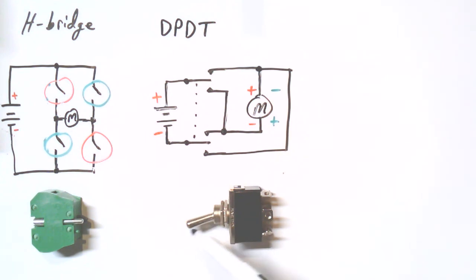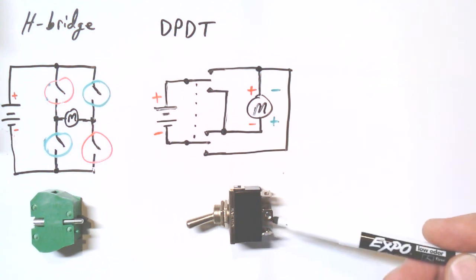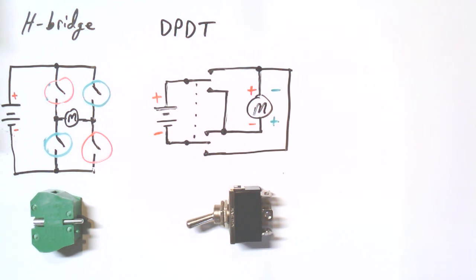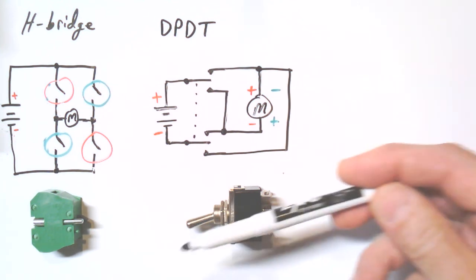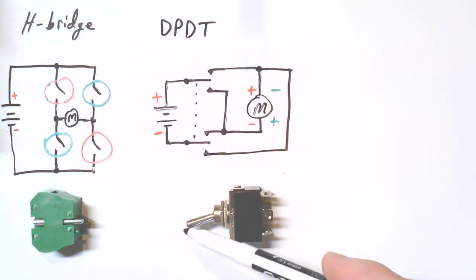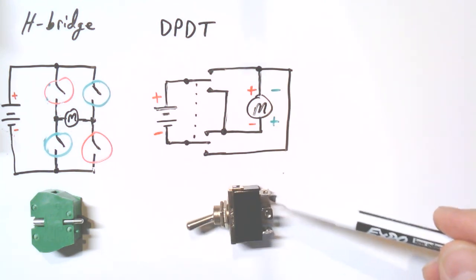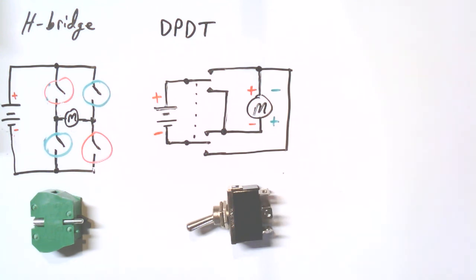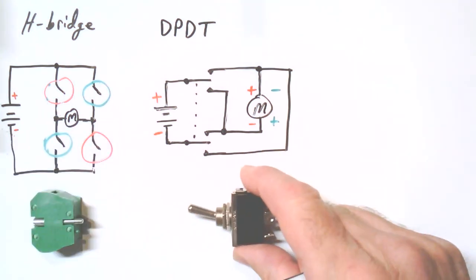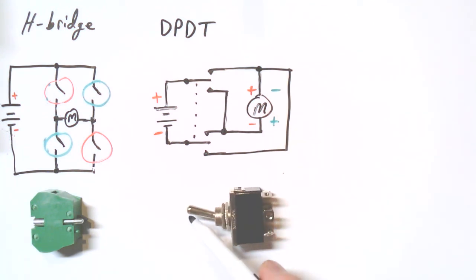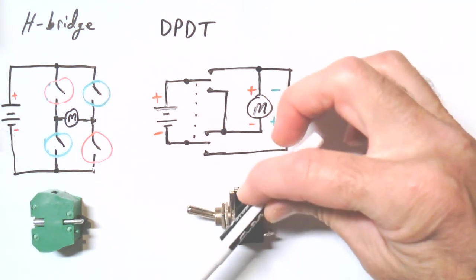So the switch is down. I mean, the lever is down. Well, if you guessed that these 2 are connected, you're wrong, even though this is down. But maybe you remembered, and hopefully you did, there is this lever that moves like this. So for a toggle, when this is down, these 2 contacts are connected. And similarly, when this is in the opposite position, if you can see, it's up, then these 2 contacts are closed, because again, this is the action that happens.